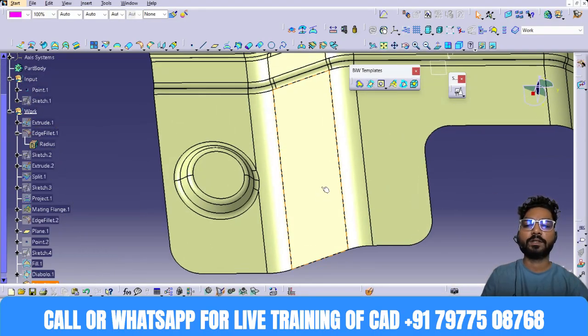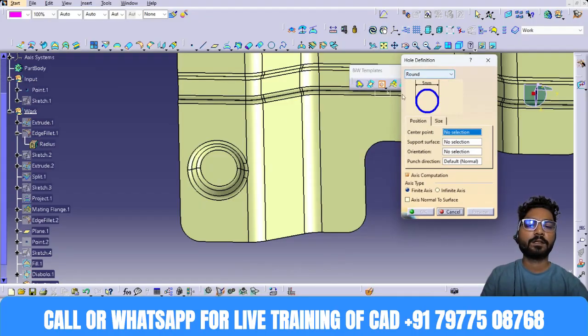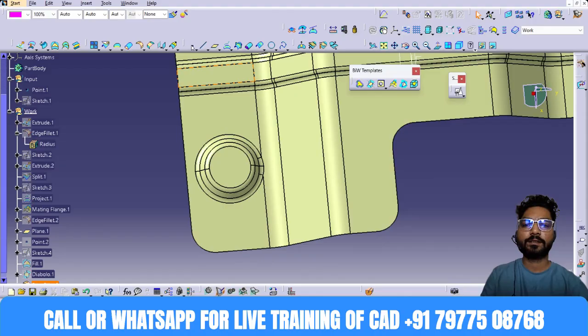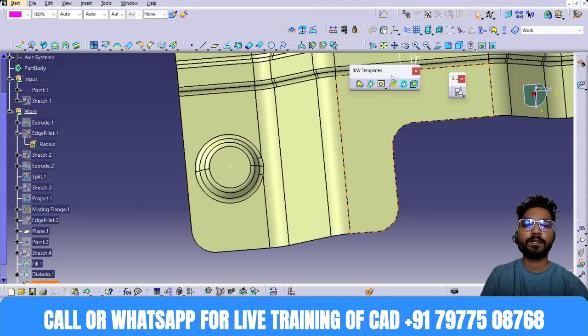And for your assembly, you require a hole, right? So for assembly, if you require a hole, what we can do here is create one hole command. For the hole, we want to create a point. So how can we create the point? The point will be created on the surface or circle, and I'll take the center of this. Then we can use this hole command.